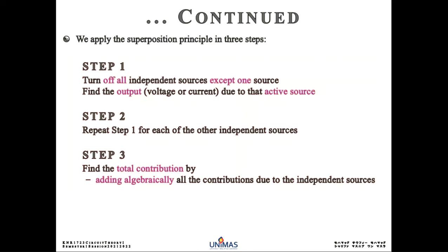Right? So what do we do? Like before, last time we had 3 steps also. Not many. All have 3 steps. If it is nodal analysis, okay, label all the nodes. One node is the reference and the other nodes are non-reference. And then you apply KCL at that node and express the current in terms of voltage and then solve for the node voltages using the matrix. The same here, there are 3 steps.